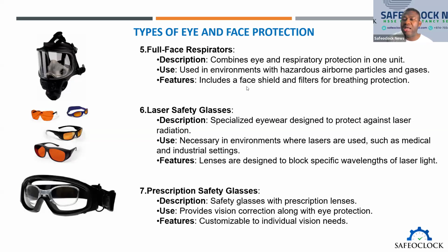the wavelength of the laser beam that is present within your industry, or within your machine. The wavelength of the laser beam that the machine you're exposed to emits will depend on the type of laser safety glasses you purchase. So each of them has varying wavelengths of laser beam that they can protect against. So you have to specifically know the beam of the equipment you are using, or the beam of the laser radiation that you're exposed to.